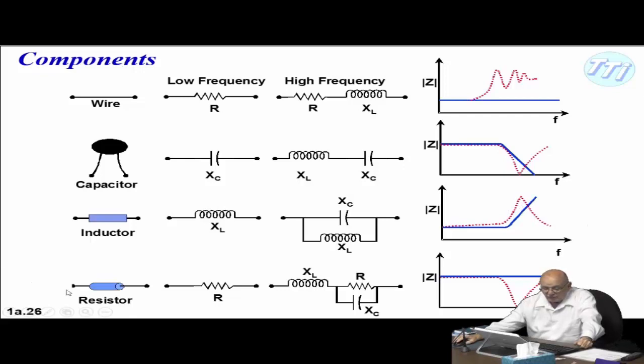Of course, you'd think of a carbon resistor, that doesn't have much with it. There's what it looks like. There's the actual schematic symbol. And then here you'll see the inductance is due to the wires themselves. And then the actual resistor itself, there's a capacitance between the two ends. That little piece of metal connecting on that end, and this capacitance. So you end up with this kind of arrangement specifically on there.